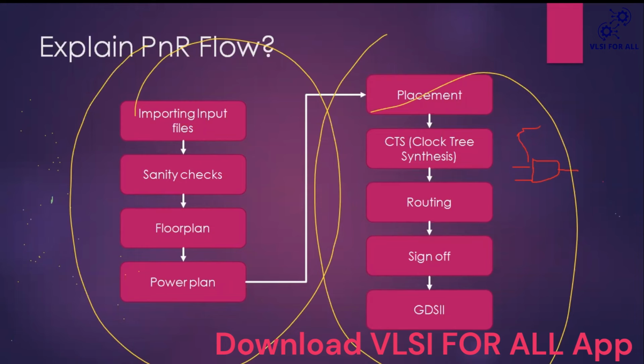I will explain properly in the scan chain reordering slide. So after scan chain reordering, in the placement itself, the tool does high fan out net synthesis. High fan out nets are mainly reset and preset, all these asynchronous pins for flip flops.